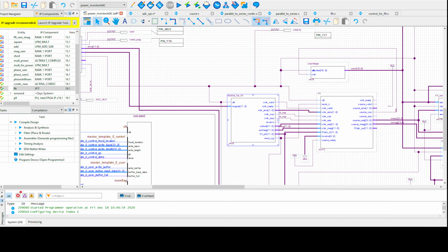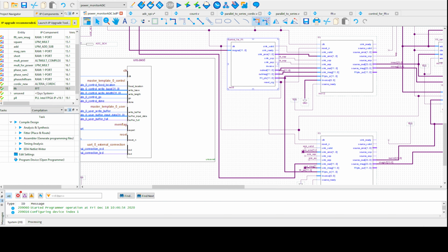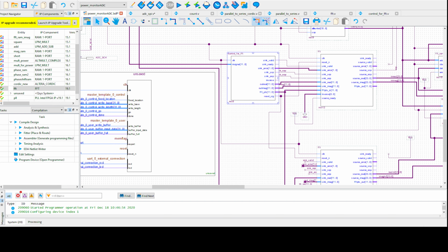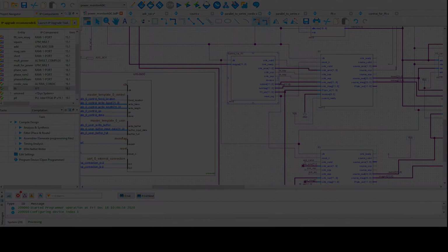So in the context of the wider design, this interface code obviously is just before the two FFTs. This should give us the sync start of packet and sync end of packet that we need. And then the next step after that is to have a look at the signals coming out of the FFT, and that should contain the frequency domain information. So we'll have a look at that next.